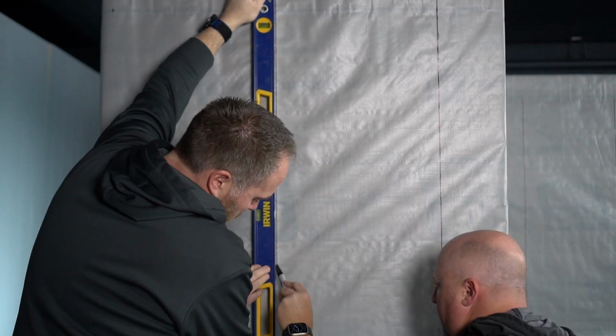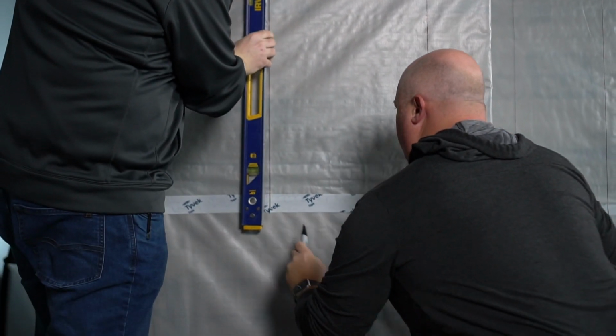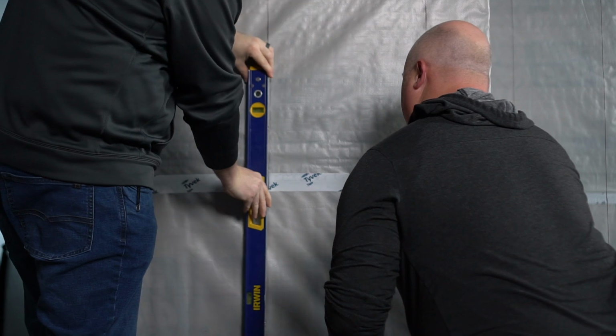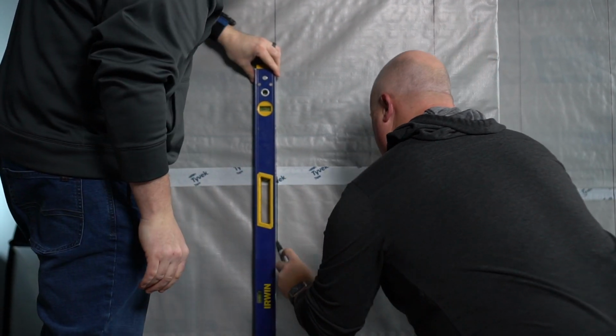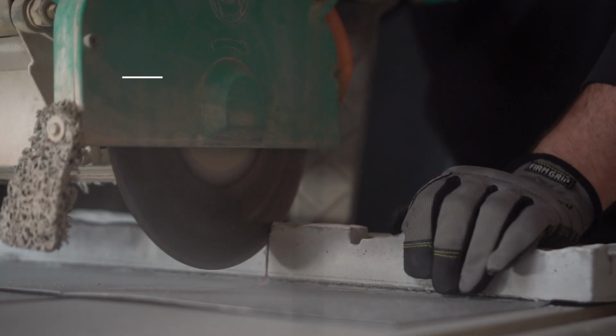Silvermine Stone panels should be installed only on homes and buildings that meet code requirements, including a single layer of weather-resistant barrier, or WRB for short. As a best practice, it is recommended to mark the location of the studs on top of the WRB. This will speed up the installation and ensure screws can penetrate a stud once the WRB is installed.